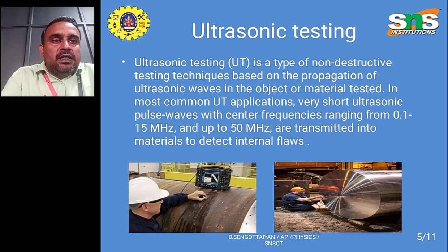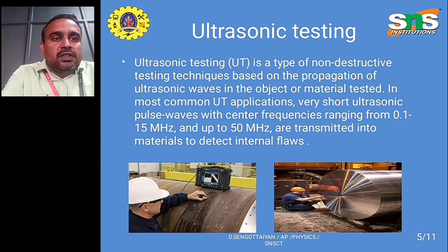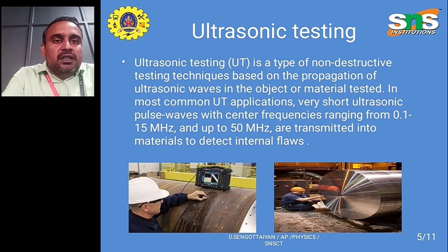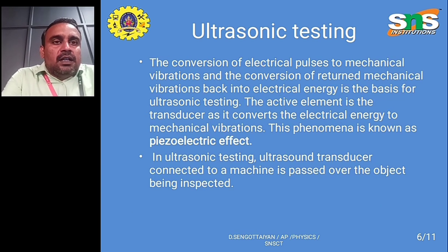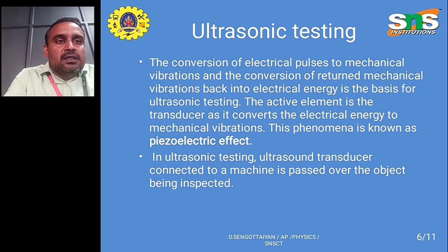Now, ultrasonic testing is a type of non-destructive testing technique based on the propagation of ultrasonic waves into the object or material tested. In most common ultrasonic testing applications, very short ultrasonic pulse waves with center frequencies ranging from 0.1 to 15 MHz and up to 50 MHz are transmitted into the material to detect internal flaws. The conversion of electrical pulses to mechanical vibrations, and the conversion of returning mechanical vibrations back into electrical energy, is the basis of ultrasonic testing.